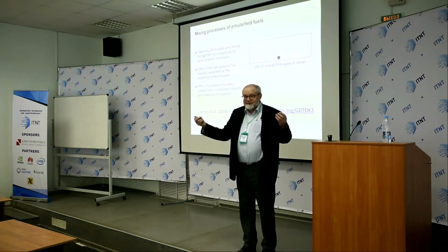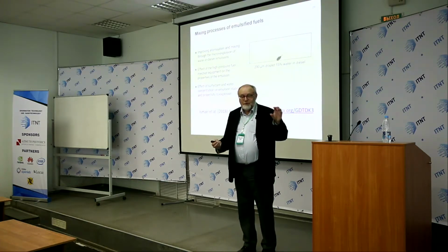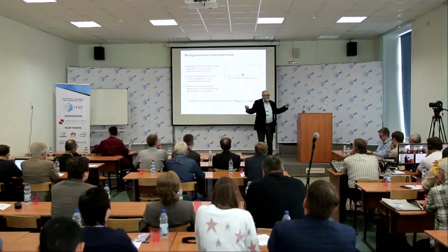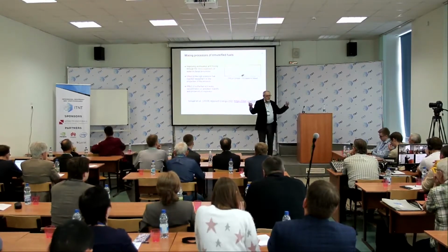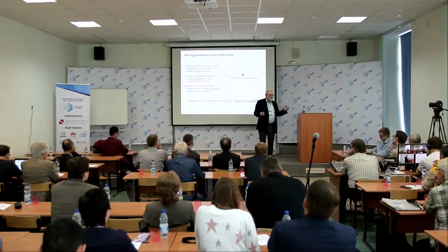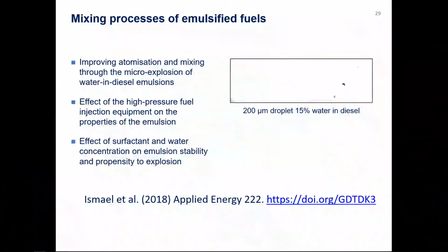And when they explode, a big fuel droplet turns into a number of very small subdroplets, very small aerosols, which evaporate very quickly, and this improves the performance of the engine. So this is the underlying philosophy behind the microexplosions. There are a number of other reasons for this, but this is something that I'm not going to discuss today.